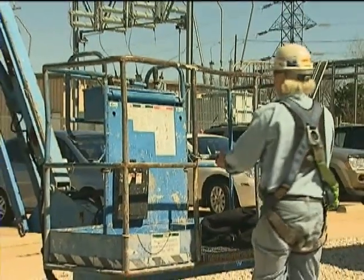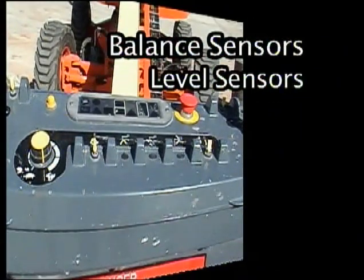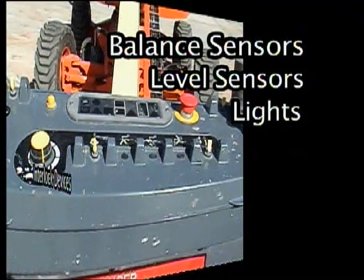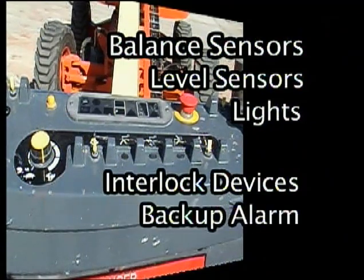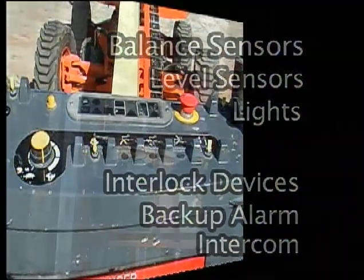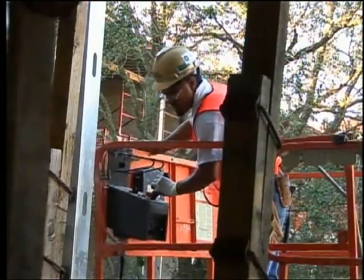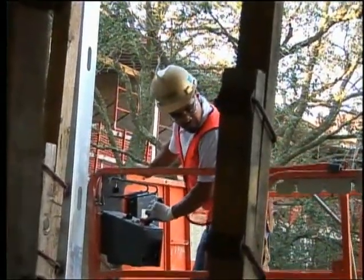All safety guards should be checked for malfunctions. Check balance sensors, level sensors, controls, lights, interlock devices, backup alarm, and intercom for proper operation. The emergency descent system should be checked by raising the platform a couple of feet and then turning the lift off and using the auxiliary power to lower the lift.